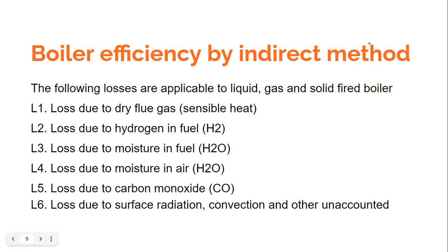Same thing about the moisture. The moisture is present in the fuel. That moisture will get evaporated and that would require certain energy. If there is moisture present in the air, then we need to calculate that loss also, right? So I would take one small numerical which would demonstrate a few of the losses, and that would help you understand and appreciate how these losses are calculated in actual practice, and that would give you the confidence necessary for doing the energy audit on your own.